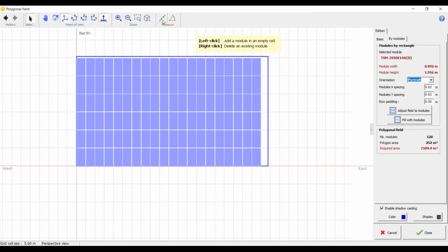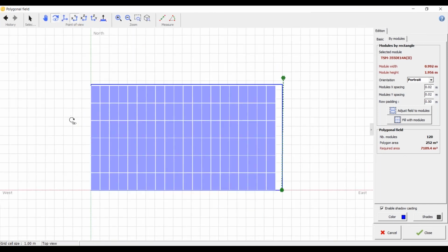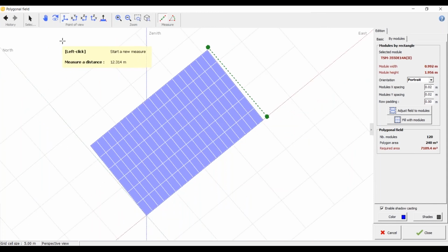So if you can see, for the plane that we created, we are able to fill in, instead of just creating a PV plane that is 12 meters by 21 meters, you can define how big you want a PV array to be. Okay, so as we mentioned earlier, this one actually takes in so many modules. If you don't want to do this, you can define a certain number of modules in the x-axis, a certain number of modules in the y-axis, and then you can change those. But in order to do that, we have to go to a different PV setting here that we'll see next.